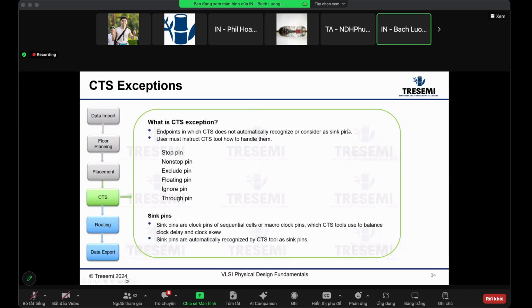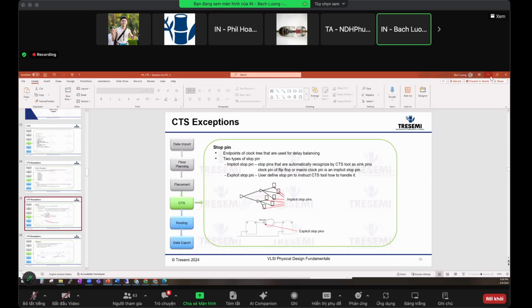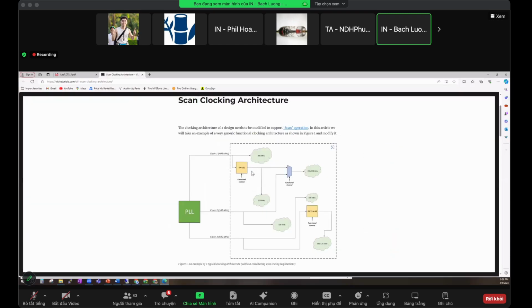Oh shoot. Okay, hold on one second. I was going to show you, okay, in this particular case you have a division by 2. If it's simple, with two back-to-back flops, then you would want to put a trace through pin on the second flop so that it can get to this mux.